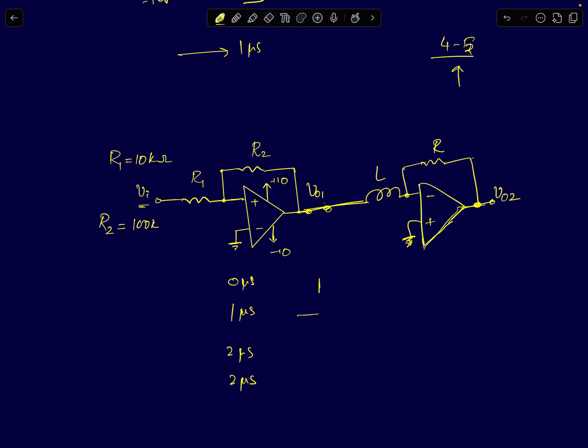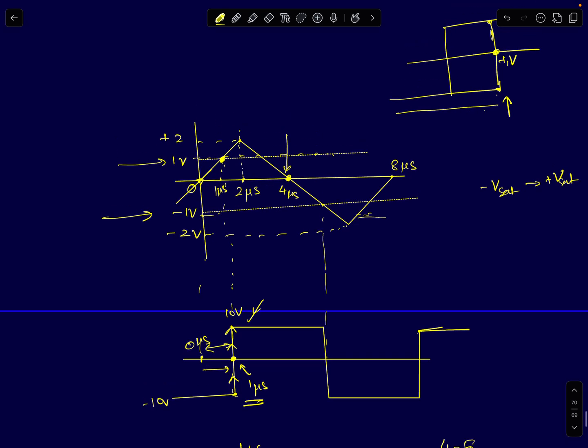So here I know the output is a pulse signal. The output here is a periodic square wave output, and the duty cycle is 50%. If you guys observe this waveform here, the input waveform has some kind of symmetry. It's a periodic signal. The Schmitt trigger has symmetric threshold voltages. Therefore, the duty cycle will also be 50%. I mean, you can see the on time will be between this 1 volt and this -1 volt. Okay, when your input goes lower than -1, your output will go to -Vsat. So that's your high to low transition point.